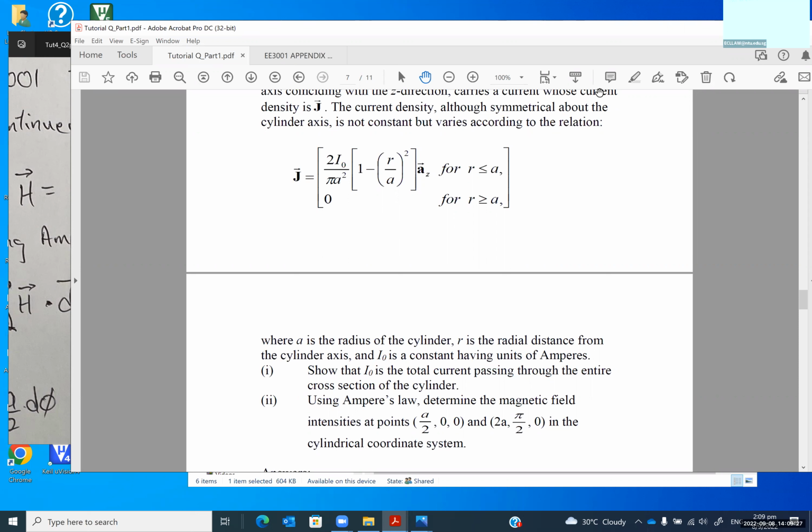After that, do we say 200 degrees? No, never say 200 degrees. It will be minus. You have to go this way: minus 45, minus 90, minus 135, minus 180. So polar coordinates always default to a maximum angle within plus or minus 180 degrees.